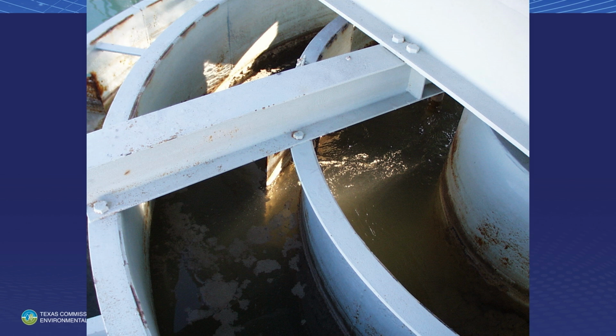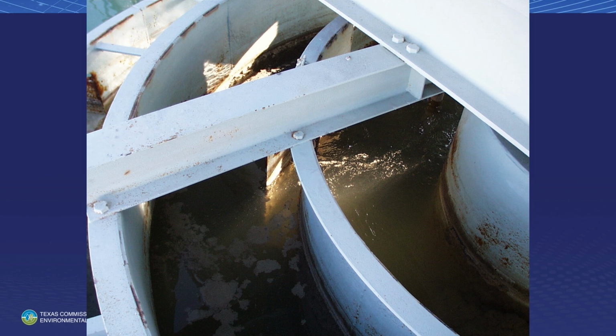If it's wide open, that water comes out of that channel, hits that wall, and instead of going in a circular motion, it goes straight down. And you lose that flocculation energy inside that clarifier. These are usually just chains that hold them on. Sometimes they're rusted in place and you can't move them anyway, but they do need to set at some kind of an angle.